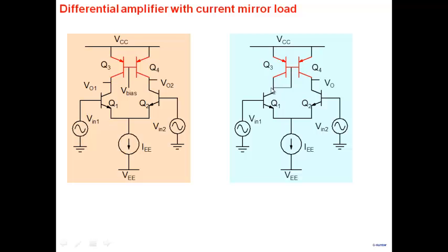As this 1 milliampere is flowing through this, it will set up a value of voltage here. 0.7, 0.68, 0.69, whatever it is, it will develop a voltage at this particular point here. Okay? And the same voltage is applied to Q4, so 1 milliampere flows here also. And so therefore, the biasing problem has been avoided. I don't need to apply an external bias voltage here. The bias voltage that you see for Q4 is internally being generated through this current as it flows. So the biasing problem has been avoided, and I'll be able to get high gain here.